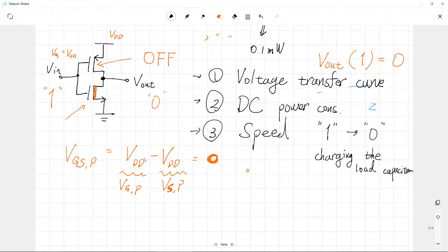But in the case of a CMOS inverter, both the NMOSFET and PMOSFET can change their conductance in exactly the opposite way. So they can give the dominance to one or the other. So now the voltage transfer curve consideration is verified.